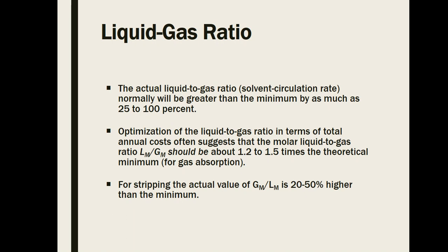So based on the range of values that we are allowed to multiply to the L prime minimum, we are using the maximum on the range, and that is 50% more of the minimum solvent requirement. Though 20% more is acceptable, often in textbooks we multiply it by 1.5.